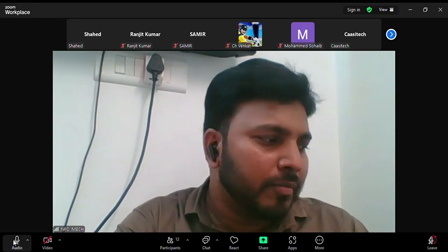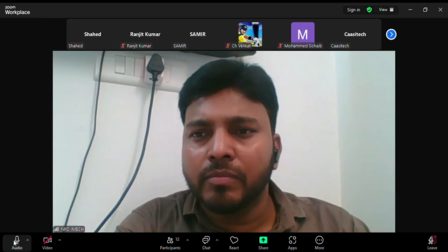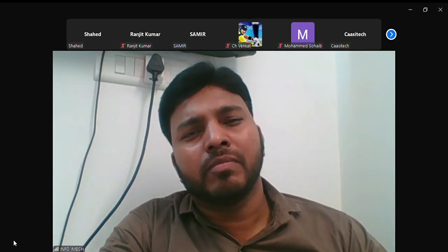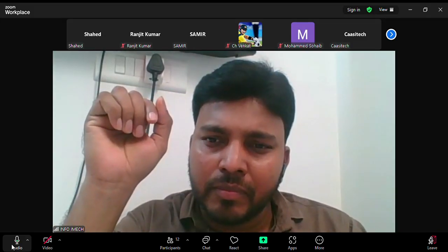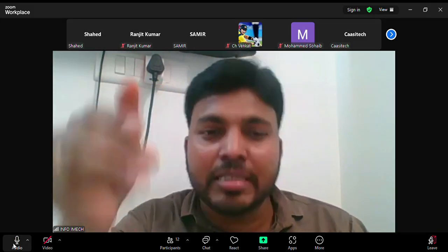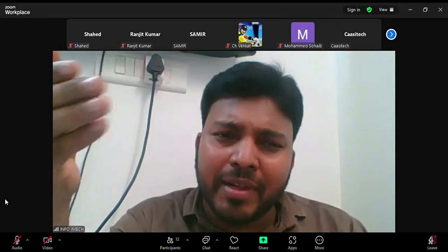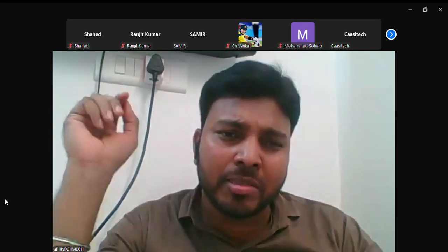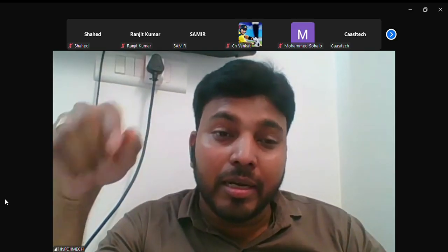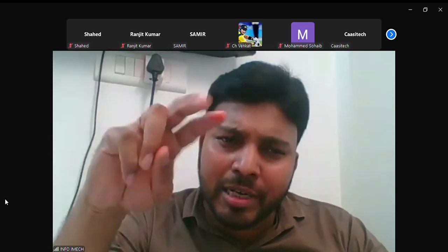Waiting for your answer. When sound touches the end of the thickness of the job, I need a simple answer. This is the answer. Obviously, when there is no defect, only the back wall echo will display, na? Sound will go the total thickness, a smooth surface. So, only two questions, guys.